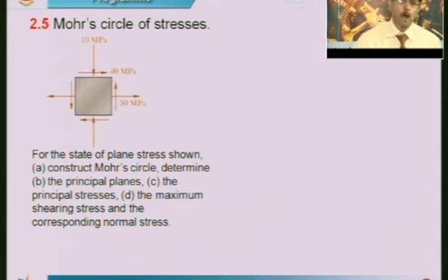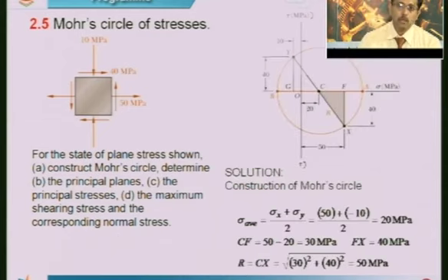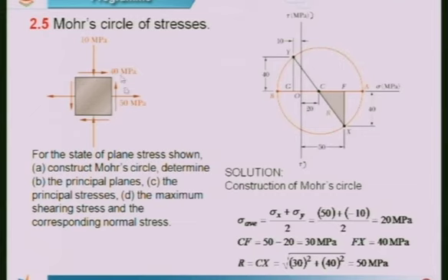Now this problem we had solved earlier also by using the formula to get the maximum principal planes, maximum principal stresses and the maximum shearing stresses. So we will take this. So in this you can see how to draw the Mohr circle for this stress block.